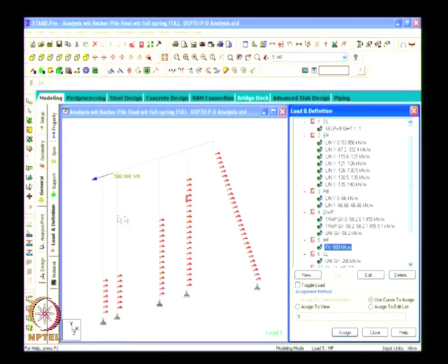3 panels we are taking, so 1500 kilonewton we are dividing by 3, that is why we are getting 500 kilonewton. Is it clear to you? The bollard pull at a particular point is 1500 kilonewton, but that bollard will get distributed to 3 panels. So each panel we are doing 500 kilonewton, but when you do a 3D analysis you will exactly get how much is going to each pile. Next.